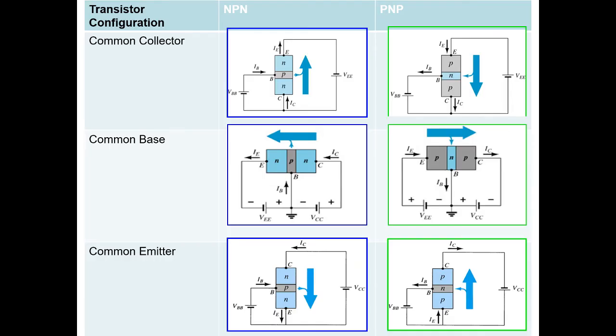Okay, if you want to connect your transistor in a different way so that you can have a different type of amplifying factor, what you can do is, for example, here I take a common emitter. Common means grounding. So common emitter means the emitter part is grounded. So for the emitter you put ground.